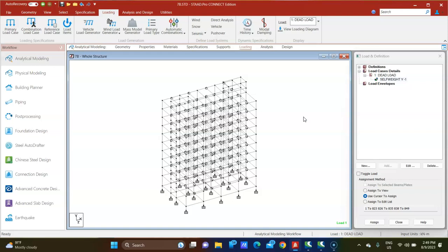And also we have calculated the dead weight of the slab, right? Or we have designed the slab and we got it. So approximate depth is 130. And for 130 depth of slab, we have calculated the raw weight of concrete. And using the floor finish that we have considered, the total is 4.25 kN per meter. So if you put that loading intensity in that frame, then Staad is capable to calculate it. Right? Let's see how to provide that one.